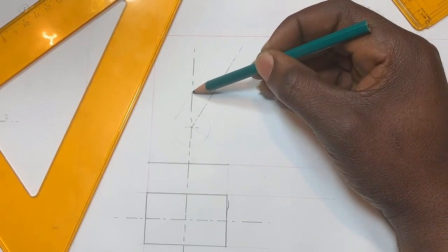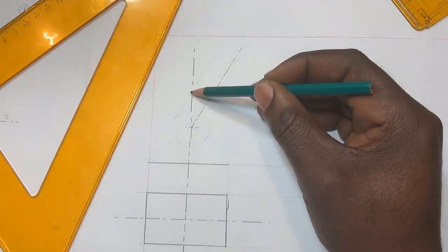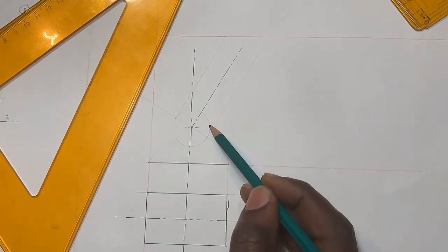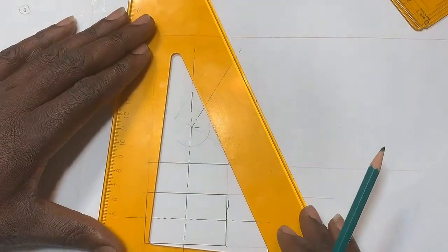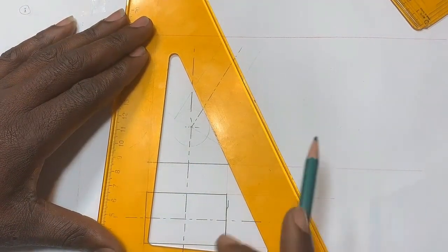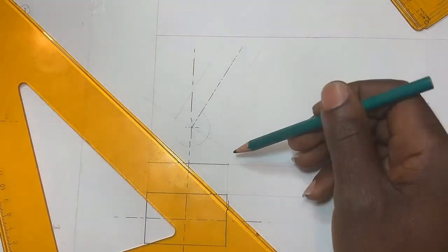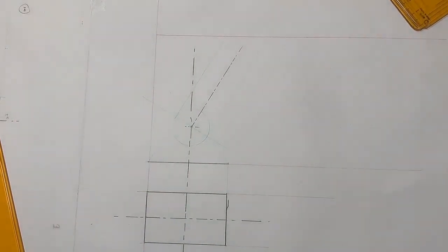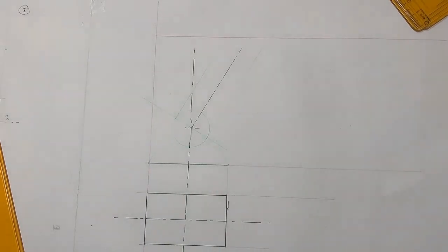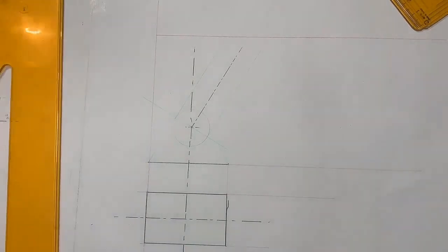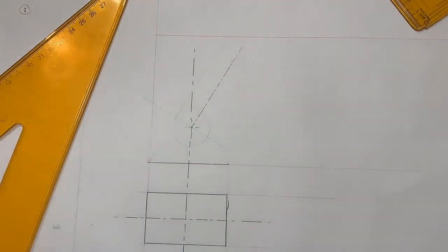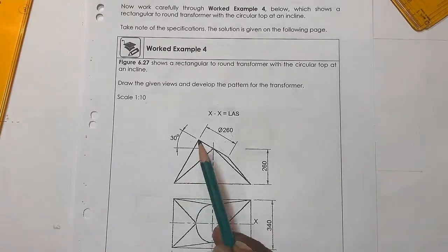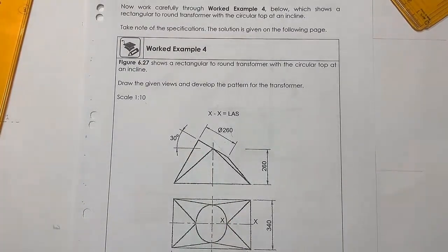Because if I'm looking for an apex there, I'll just draw a line tangent that will just touch this circle, the circumference this side and the circumference this side, like this. There you go. But then that's not what I'm looking for. Remember that it's then at an angle of what? Of 30 degrees, which is this one. You understand? So then after I've gotten that, what can I do now? Remember what we are drawing. We are drawing this, the front view. So that angle 30 degrees, we've already tolerated it.